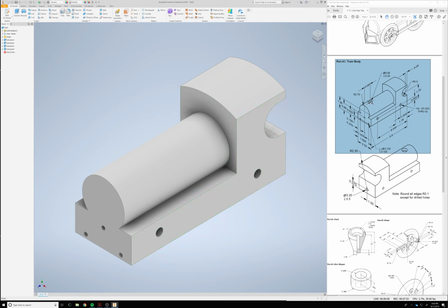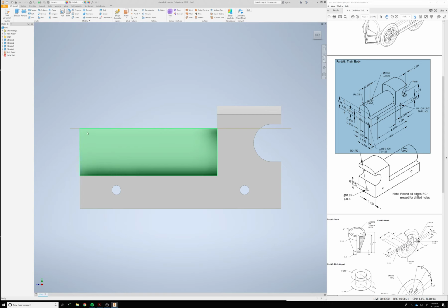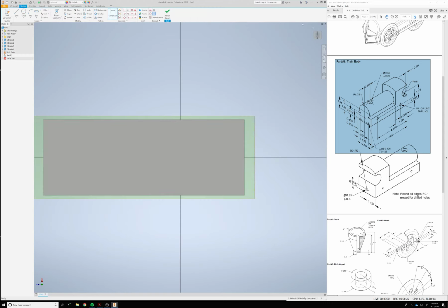We're going to put this hole on the top and then the hole in the back. Okay. So we can't create a sketch on this curved surface, so we are going to have to create a plane. So I'm going to click on the pull down menu on plane, and I'm going to select tangent to surface, parallel to plane. So it's going to be tangent to this surface and parallel with this plane, so that way if we look at it from the right, it's barely touching the top of it. So I'm going to click on that plane, and I am going to create a sketch.